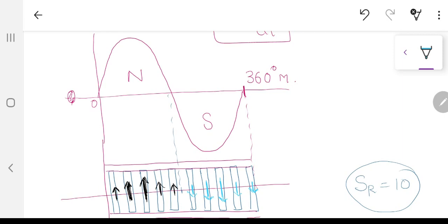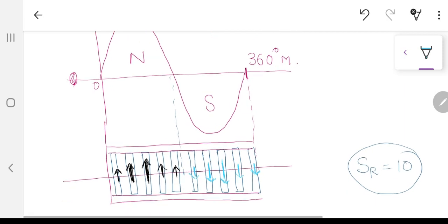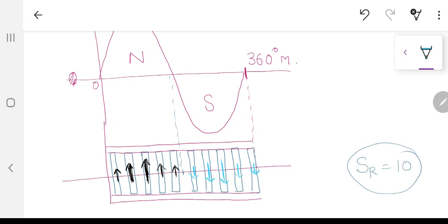It is a 2-pole machine, so it's going to have one north pole and one south pole. And I am assuming that it has no harmonics involved. I'm just taking the fundamental over here. So it's just north and south pole, and the MMF waveform is changing sinusoidally. Now when this is changing sinusoidally, you are going to have these black color bars giving you the direction of current in the bars. The light blue color over here shows the direction of the current in these bars below. So this means that in front of these bars, the currents are decided.